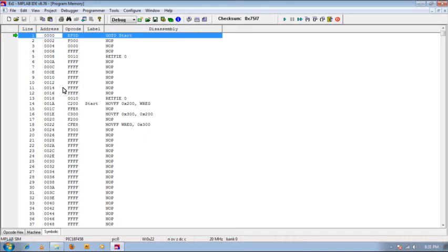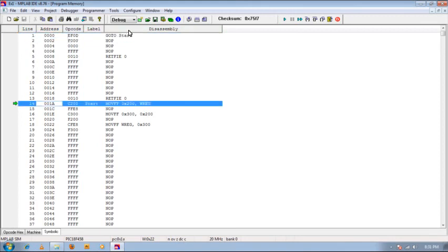If you start to execute, let's say now F6, then if you press F7, you can see at address 00 you have this code. This opcode represents this assembler directive, which means go to start. When you press F7, you can see the start label is here and another label is here. It works in pairs. Immediately go to start means your PC will point at start. The start label and the first instruction are at address 001A, and you can see your PC pointing at address 1A.